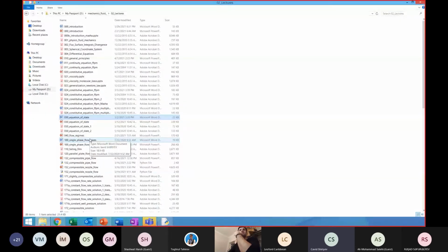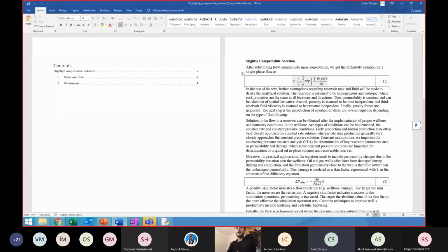Now this is the final form of the equation that we will try to solve by steps. This is the final form of the solution equation for the single phase flow. For several sessions we are going to talk only about the single phase flow, and in this single phase flow we are going to assume that we have the incompressible fluid, and incompressible fluid means that rho is constant. And if we take out this density from this equation to the left hand side, and the same thing for the right hand side, then those rho's are going to cancel out.